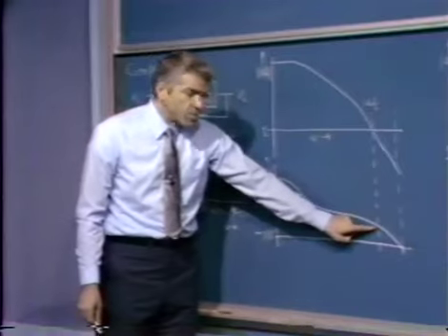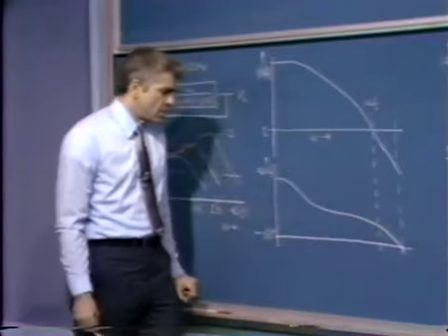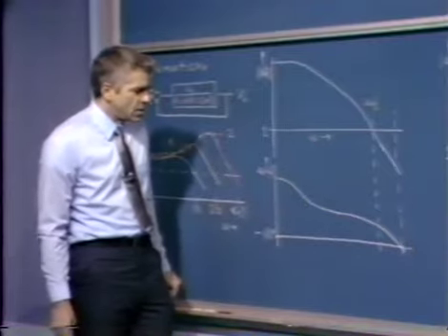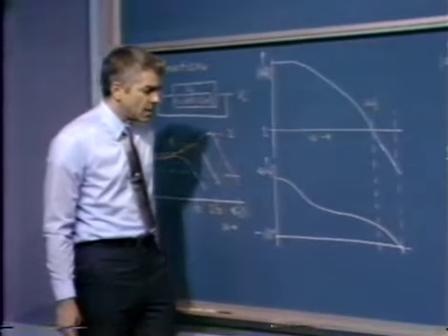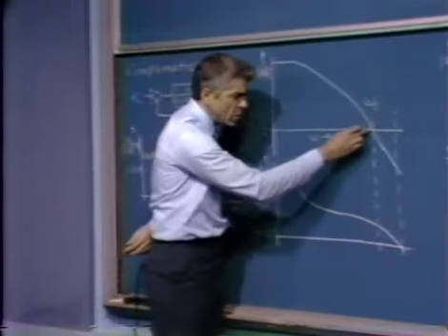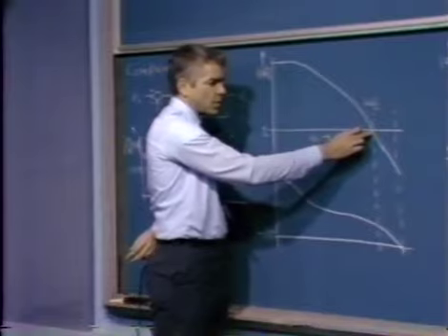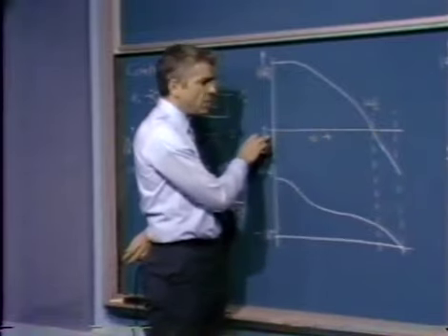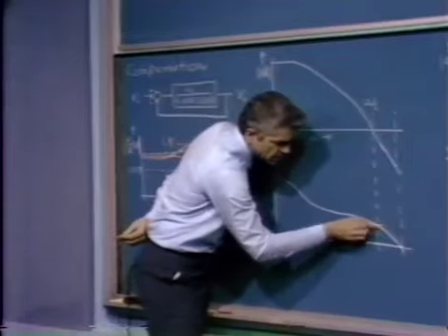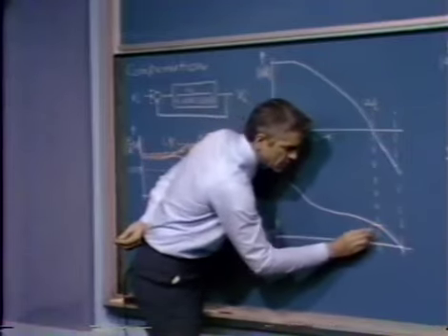The angle is somewhat more positive than minus 180 degrees. And for this sort of a simple, well-behaved system, that guarantees stability if we conducted the Nyquist test. Once we've convinced ourselves the system is stable, we can look at the crossover frequency. In other words, look at the frequency where the magnitude of the AF product is 1, and this distance is the phase margin.